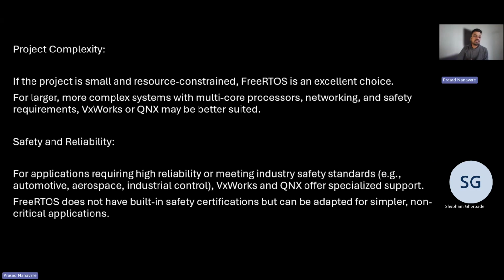Then the selection criteria we studied. In selection we talked about project complexity and safety and reliability. If the project is small and resource-constrained, FreeRTOS is an excellent choice. For larger, more complex systems with multi-core processors, networking, and safety requirements, VxWorks or QNX may be better suited.